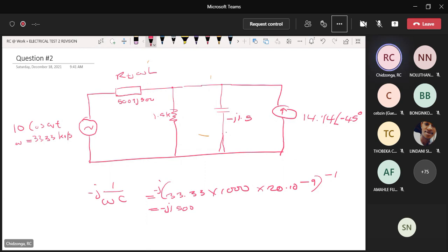right? Because I've left this in milliamp, all the calculations I do here, I must change my impedances to K, because I'll divide by 1.5. So whatever current I get will be in milliamp. So I'll go back and express this one as 0.5, this one as 0.5. So all my impedances are now in terms of K. And we are required to find that voltage.